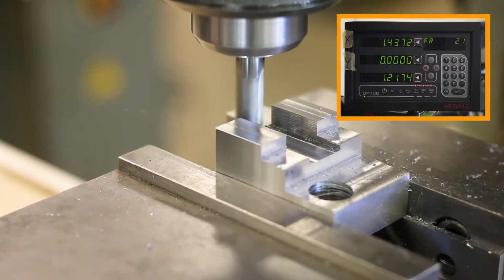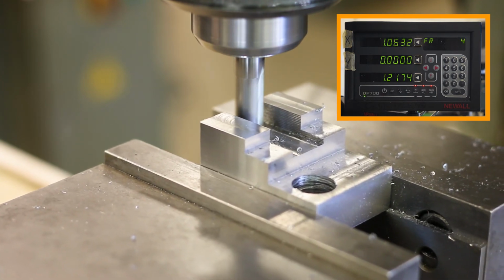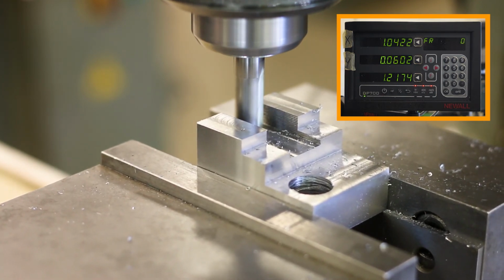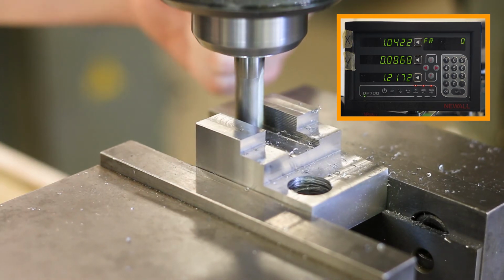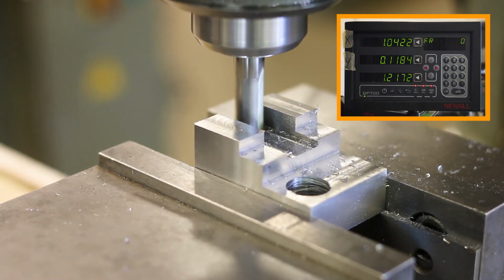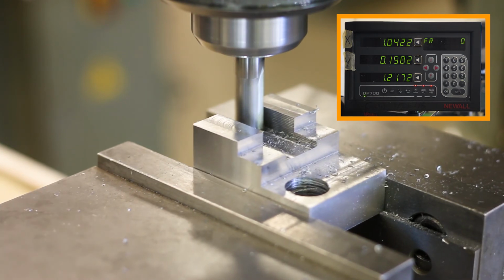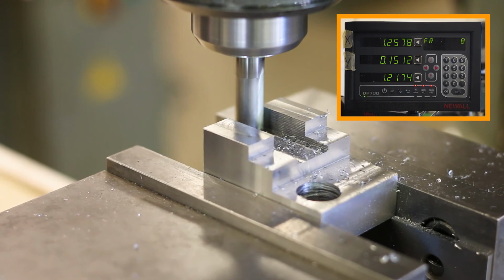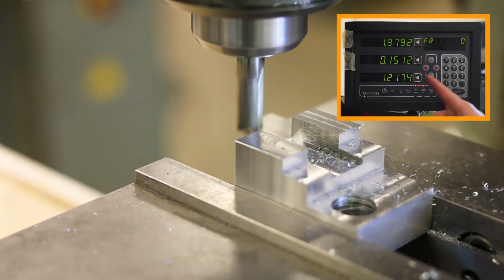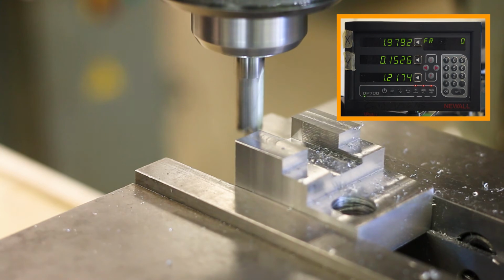Okay, I'm going to come over here, feed in a little bit, and then I'm going to feed in to the surface here on the back side just until I touch off. And right there. Okay, now feed off. So I'm not going to re-zero the digital readout. I'm just going to look at the number that I have on there. Okay, so I'm going to go ahead and take a cut at 155. So right there. And I'm going to take a cut across that surface.